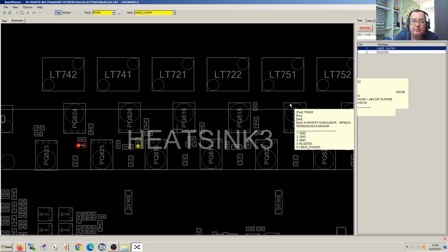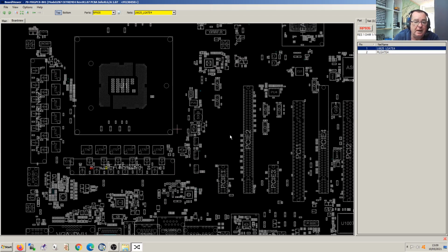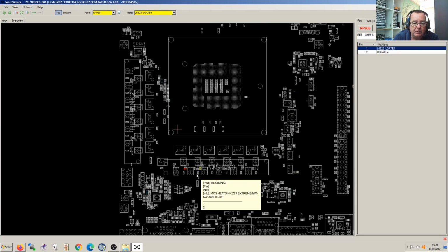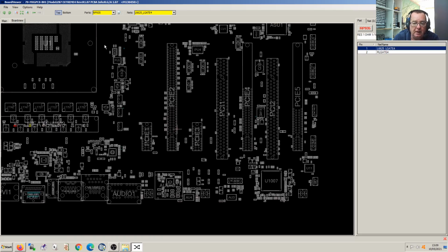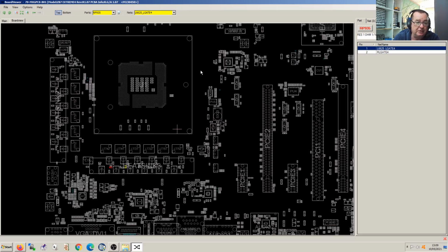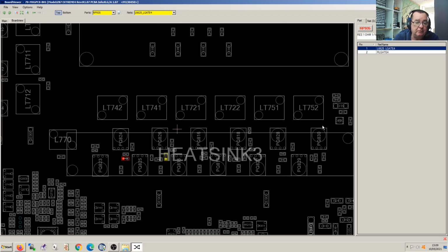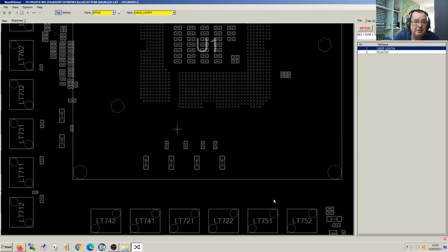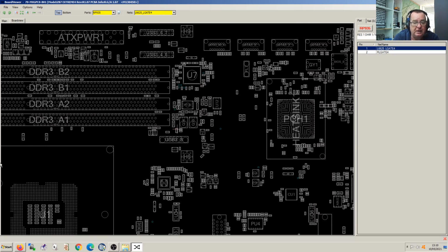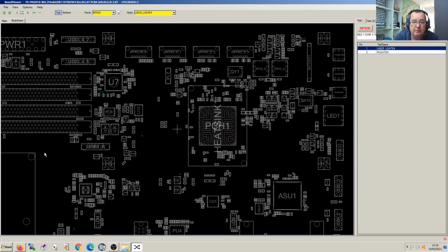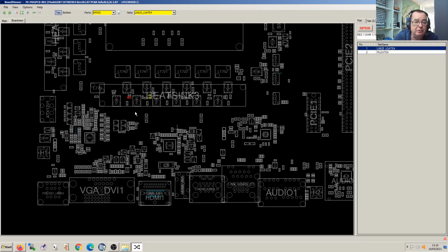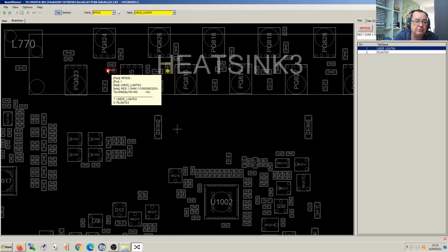Where does it come from? Well, we can zoom out, and now you can see there's a yellow and there's a red. So we know the gate drives there. We know it must come from somewhere. The VRM controller, we can assume, but we can't see it going anywhere. Look, I'm zoomed in there. Everywhere I go around on this board, I have to zoom out a little bit. Everywhere I look on this board, I cannot see where that's going to. Nothing else is in yellow. But we know it must go somewhere. The gate driver's got to come from somewhere, yeah?